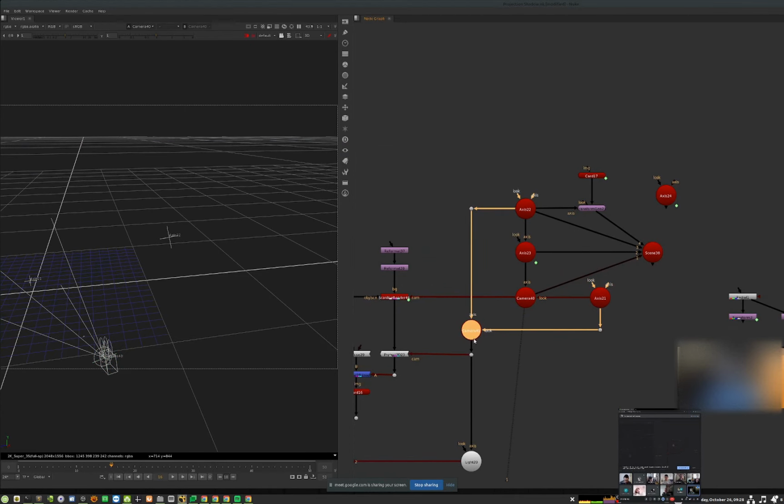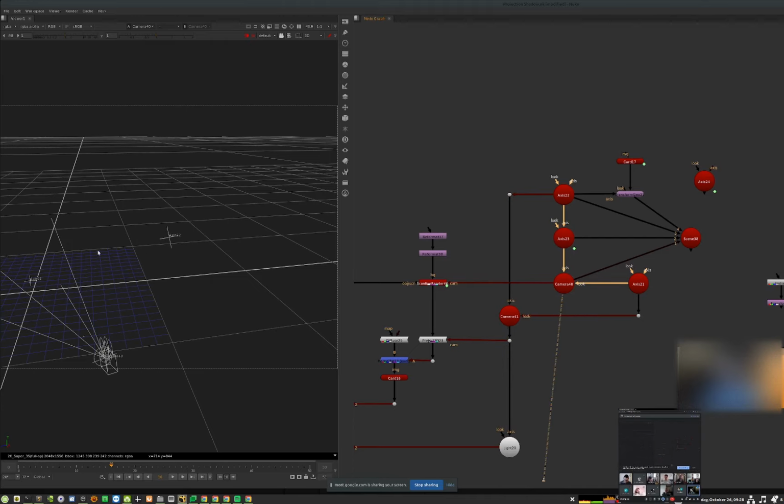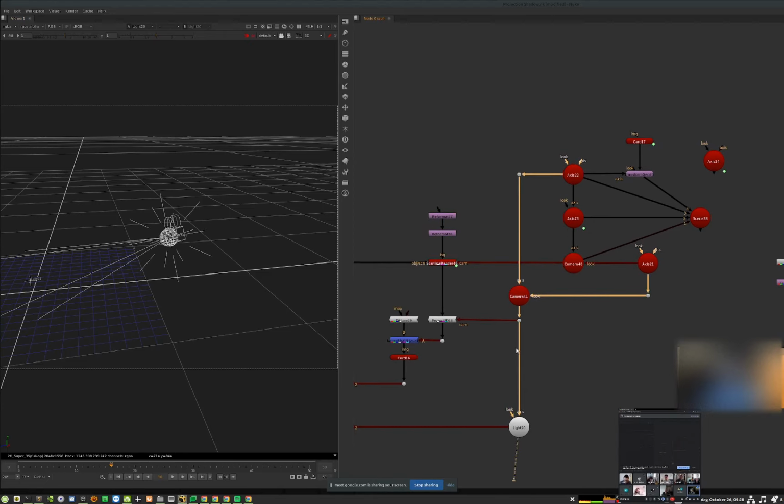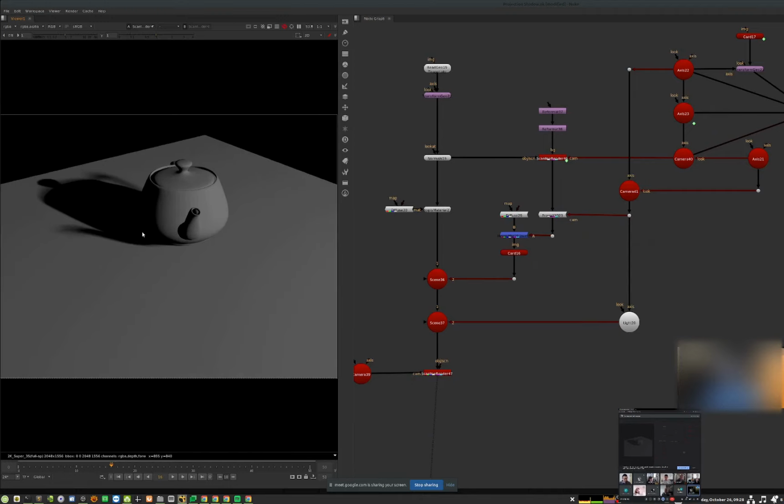But then, I want to have another camera to reproject it again on the plane. So I'm only going to do it on the shadow map, just to cut corners. And this camera should not move. It should stick to the center of the world, unlike this camera that is moving around. And that's why I have those two cameras over here. Both of them align to the origin of where I want the camera to be. One will move and render for us the scanline. One will put the light in the right place and will project again. Okay? As I go to this result, I have this effect.